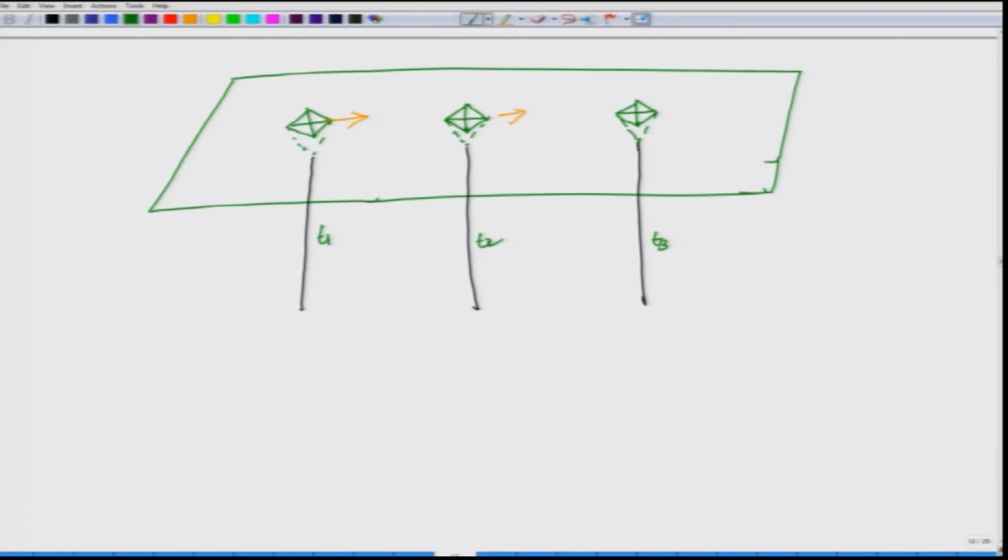So it will get a flat bottom. After the third time interval, when you etch it, you would see a much larger etch pit over here, but with a flat bottom, because the dislocation has moved out, and since this one moved out only a short time ago, you would see a smaller etch pit with a smaller bottom surface.